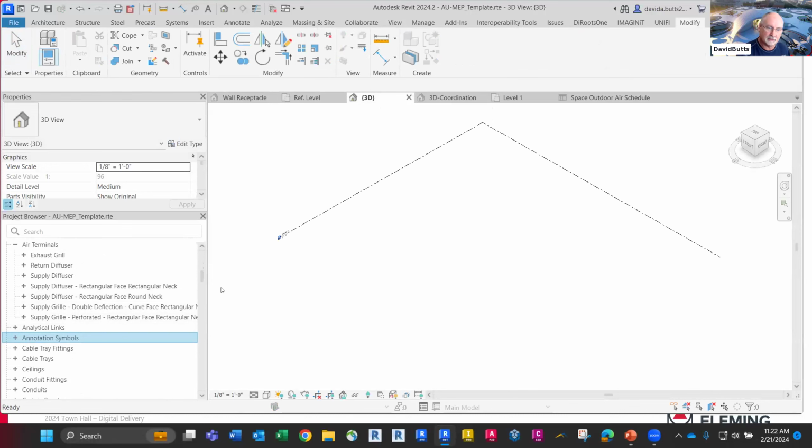At some point, you have to clean out, start over again, create a new template, and then actually pull the data in so that it's current and you're actually using current features and benefits, as opposed to something that might have been available in 2009 but is no longer available, right? And so I look at the most common items that are going to be in a template. And there's one rule of thumb I have. If there's a family that I need to have a type mark assigned, I put that in my template for my most common objects. Now, why do I say that?